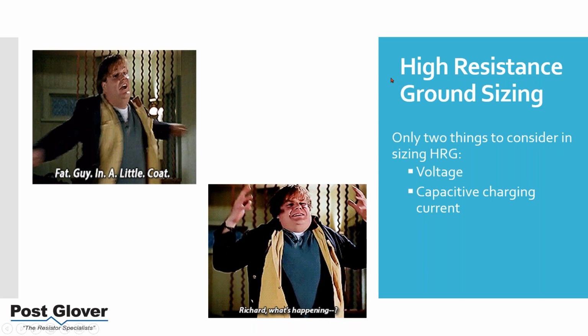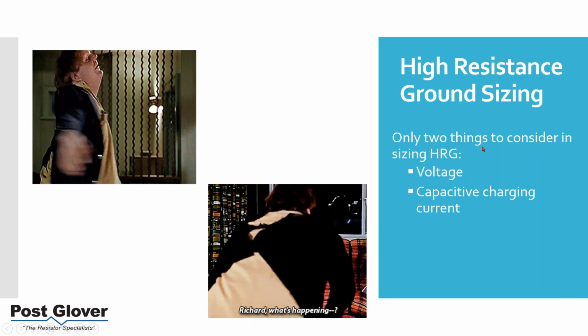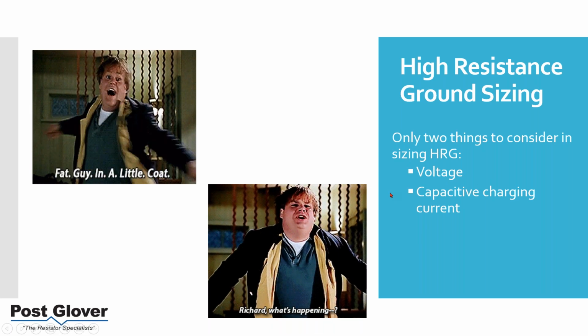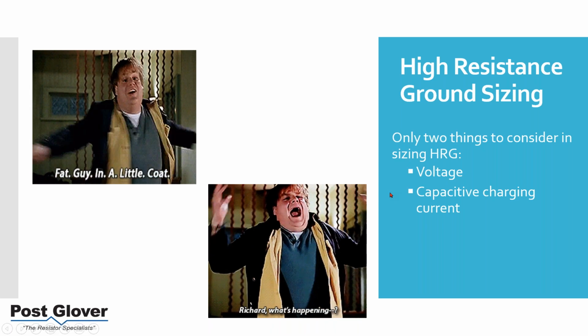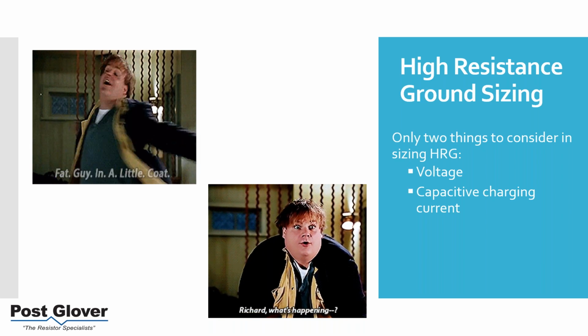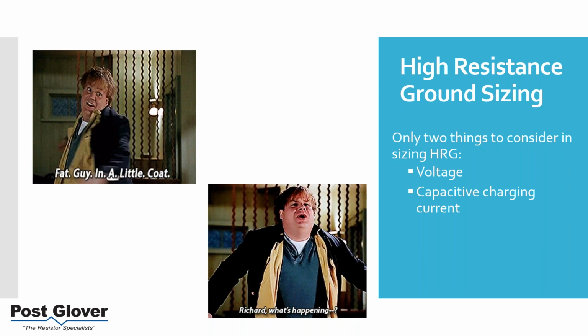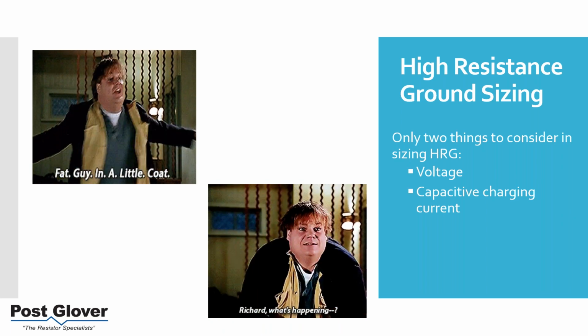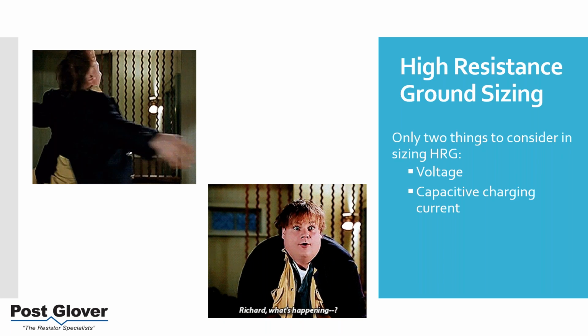So you need to worry about this. I would say on the low voltage side, most likely you're not going to have issues with capacitive charging current because the cable is not large enough, and that's at lower voltage. But that being said, I would recommend some flexibility there. That's why we have that tappable resistor.